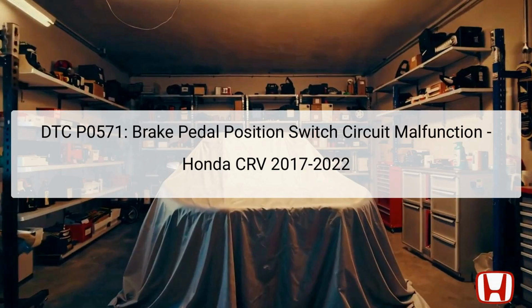When the brake pedal is pressed, this switch sends a signal to the PCM, which then controls various functions, such as the brake lights and cruise control settings. If there's a malfunction, it can result in the brake lights remaining on or not operating at all, making the vehicle potentially hazardous. The brake pedal position switch is typically located near the top of the brake pedal assembly, where it detects the pedal's position changes when pressed. Understanding the implications of this DTC is crucial for ensuring vehicle safety and operability.